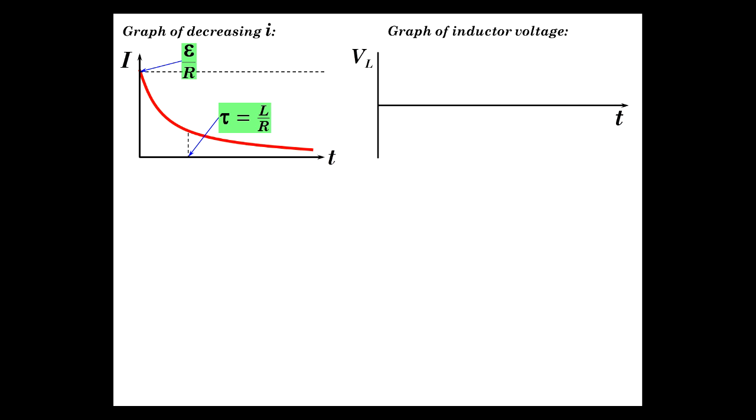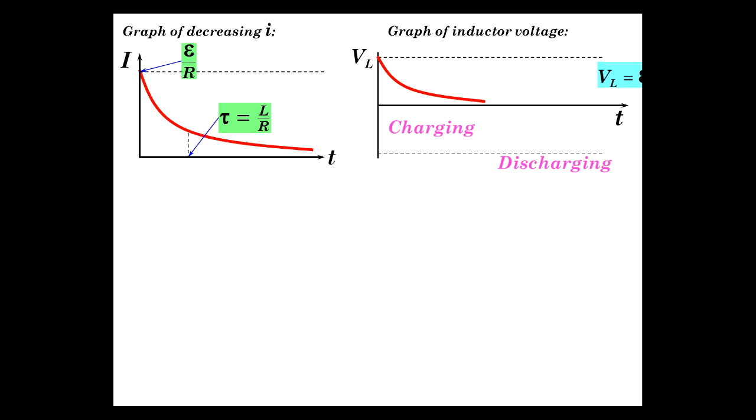If you look at the voltage, consider the voltage across the inductor. During charging, initially we had maximum value, positive, and that diminished down to 0 as the dI/dt reduced. Now why does it reduce? Because as the current increases, the voltage drop across the resistor increases, so it's fighting the source, and so the voltage across the inductor doesn't have to do as big of a job because the resistor is doing a lot of it, right? And then, however, as soon as you flip the switch, now it's all up to the inductor to produce the voltage that drives the current.